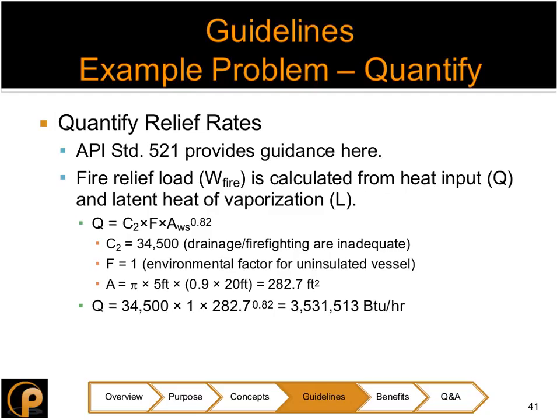Okay, thank you. Please speak to the process of marrying up PSVs into a flare system design. What standard and guidelines are there to assist in these calculations? API 521 is usually the place that we go to talk about how we marry, for lack of a better word, PSV discharges into a disposal system. The exact calculations required to do all of those things are a bit left open to the user.